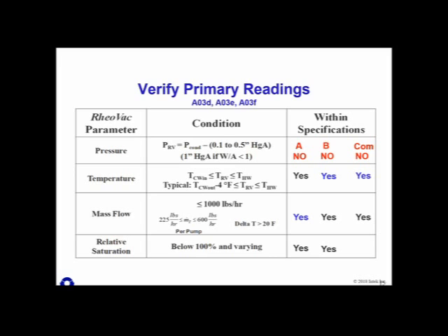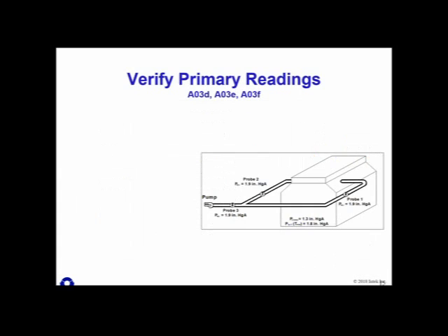No, right. Wow, 3 independent instruments all recording a pressure that is not lower than the condenser pressure. That's a bit odd. So let's put this on a plot. Here's the probe pressures: 1.9 inch from probe 2, 1.9 inch from probe 3, 1.9 inch from probe 1. So all of them in agreement, all in the same line. That's exactly what we would expect to see. But why is it higher than the condenser pressure?